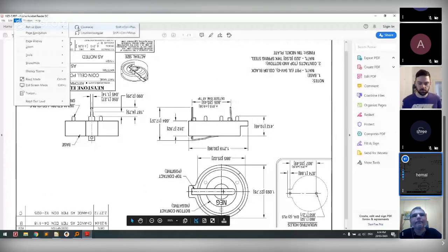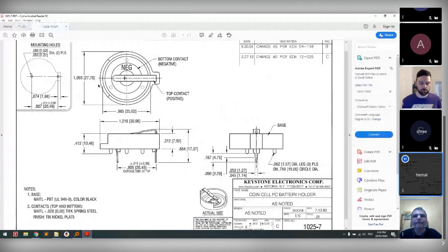The only time you want to use STEP files to be converted into footprints should be rare. You should always follow the data sheets to draw your footprints. But under certain cases, when certain data is missing, you would need to go this route. As you see here, this whole battery holder doesn't sit flush with the PCB. So there is an offset, and there are some posts here which are above the PCB.